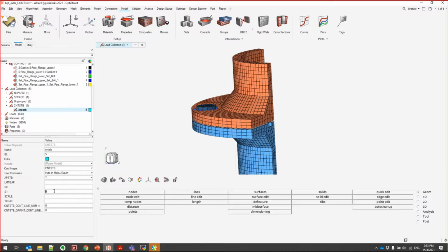But if at the end of your run you still find that something is very hard to converge, then you probably want to add some very small value here. So yeah, you can turn this on. Now we already have the Expert NL. Expert NL is by default, so you cannot adjust the values there.